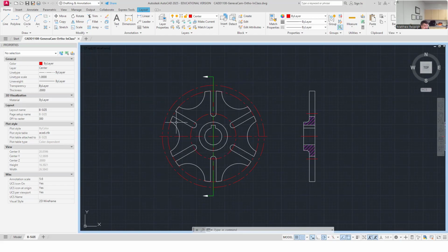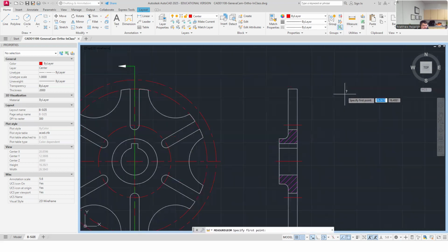It's just the practice of going through size and location, and I start with overalls. The overall size is going to be a height, a depth and a width. So here's my width and here's my height, and my depth would only be shown on the section view. If I look at overall width here, it's kind of a diameter. The thing that's controlling the overall width is a diameter. The only place that the true diameter of the part size I need shows up is this front view. I don't have it here, because this section view is slightly shortened.